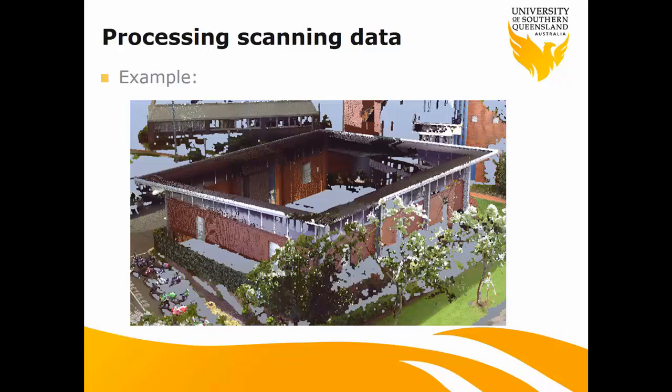During the registration, if you like, you can select to extract the color information from the digital photos and apply it to the individual scanning points. Certainly that will take extra time, but once you've done this, it will help with the following processing, for example classification or modeling, compared to black, white, or gray scanning points.